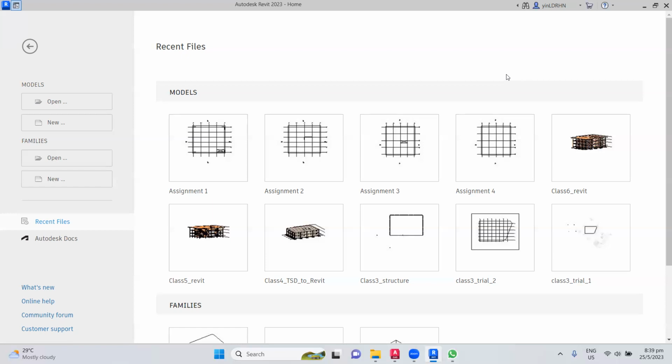In concrete, there is no correct or wrong. Concrete depends on the rebar density. Let's say a column: if you go to a maximum rebar density of 4%, you can reduce the column size. But if you want to minimize the rebar, let's say 1%, then you can increase the column size.